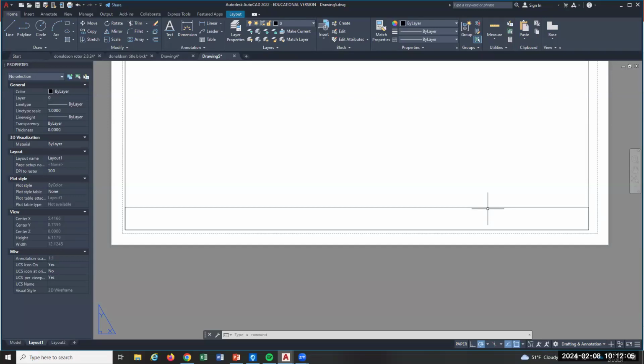All right. Offset. Have you used that yet? It's a power command. So offset. Where is it? Show me it, people. It's right there. See it? Offset. I don't do the buttons. I would go FF, and it would pop up and I would use it. Okay, so offset makes a copy of an object at a distance. If it's a circle, it's going to make a copy at a distance. If it's a line, it's going to make a copy up or down or right or left at a distance, right? So it's like the copy command, but it's a lot more powerful because it's faster.